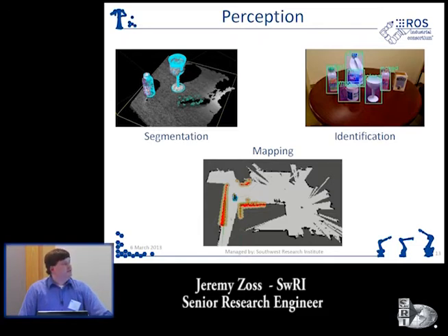It hadn't really been mentioned, but there's a lot of capabilities in there for mobile platforms about automatically building up a map of your environment and learning how to localize yourself within that map to help maintain a good state of where the robot is in its environment. A lot of that's been developed for the 2D environment, but there's similar kinds of capabilities for a 3D environment also. So that might be a robot that's trying to enter a new environment or a confined space. If it's got a 3D sensor on the end of it, it can scan its environment on the fly and build up this map to know, say from an obstacle avoidance perspective, what kinds of things it needs to avoid.